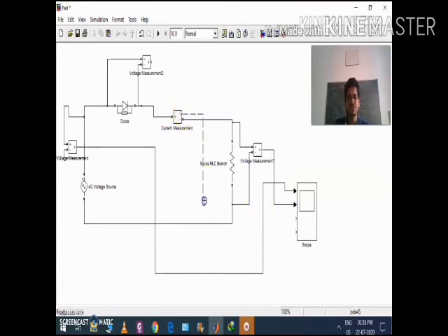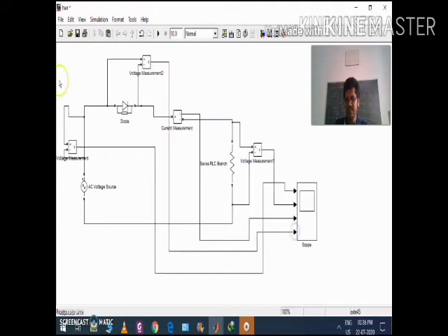Now again I will take this and connect it here. I want to measure current in the circuit. The current in the circuit, V0 and I, are the same. Why am I saying this? I am using the small shortcut of Ohm's law, V equals IR. It is only for the resistive load, not for all loads. So the V0 waveform is the same as the I waveform, so there is no bother about it. I would like to find the voltage across the board.